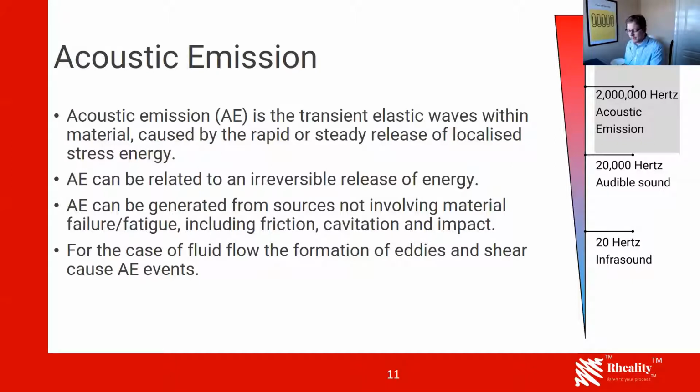As said, you might have had it yourself in one of your application fields or workplaces. It is very traditionally used to look at material fatigue or material failure, and welding applications, but also things like friction, cavitation, and impact actually give you those acoustic emissions. For the case of fluid flow, we know what drives that event: the formation of eddies and shear boundary effects along the boundary layer.